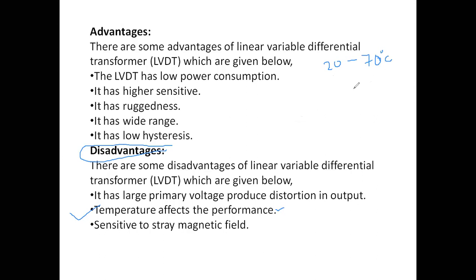And there are some LVDTs which can withstand up to 100 degrees centigrade also. From 10 or 20 degrees centigrade to 100 degrees centigrade also it can withstand. Means these LVDTs have good temperature shielding also. But even then, if the temperature increases beyond the limit, then it may show some error values.